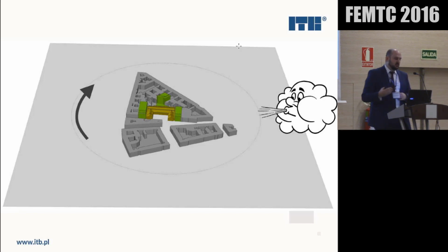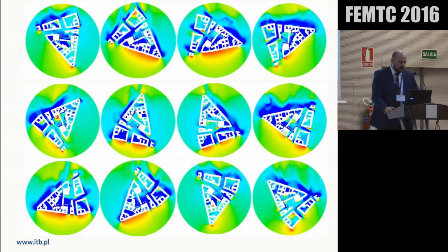I guess there are ways around it. You could just use angled wind, angled velocity profiles on your boundary conditions, or you could go with the method that was shown yesterday, where you choose the worst case based on the wind climate of the area. But it's really important that you model at least some wind angles. Why?